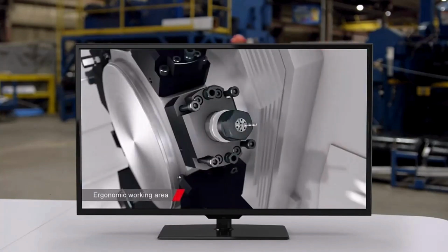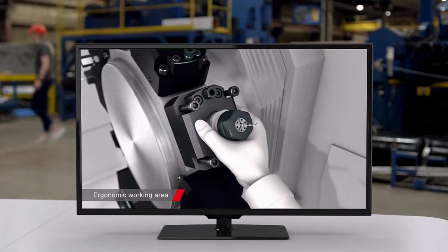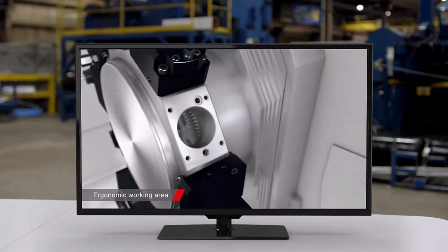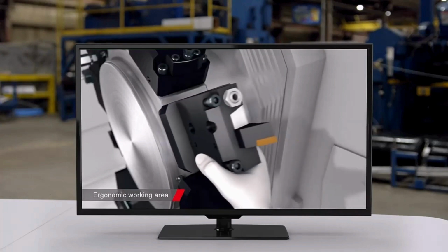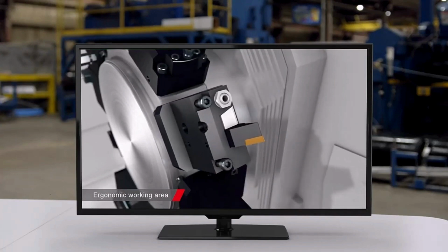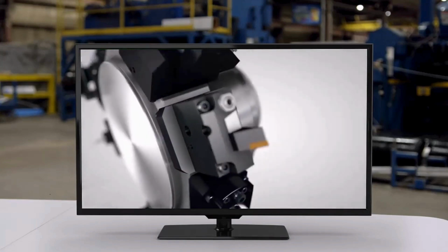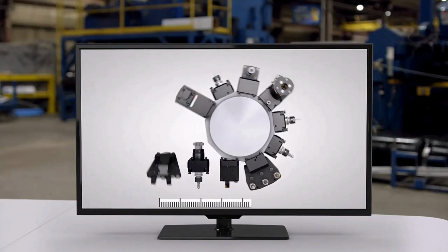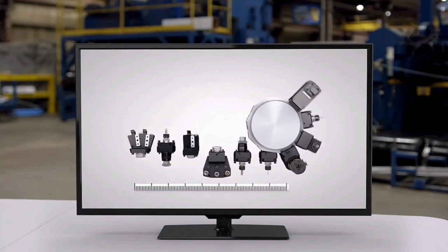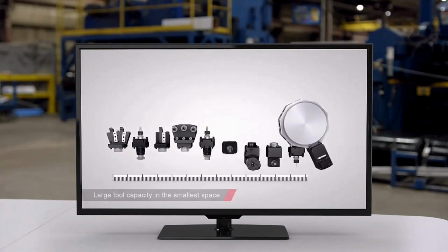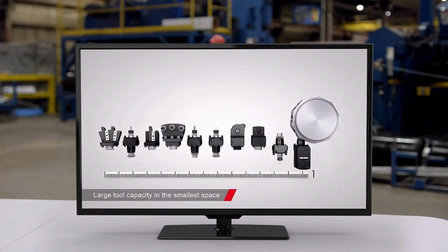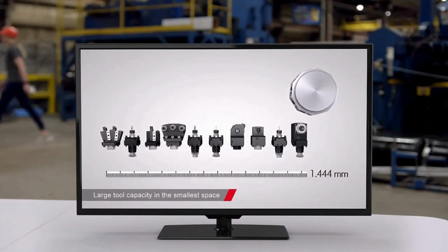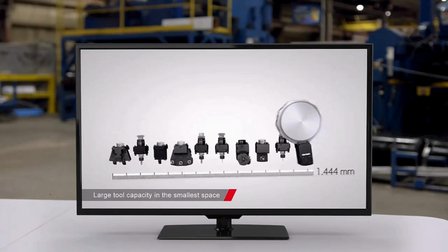Notice the tool mounting blocks on the turret. These are interchangeable and can be replaced with different mounting blocks suited to hold different types of tools that the machine can use. When we consider implications on post-processors, many post-processors that have graphics will include the graphics of the turret, but do they include the various tool mounting blocks or tooling program used in the customer machine?